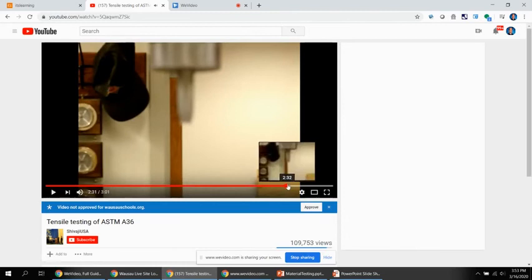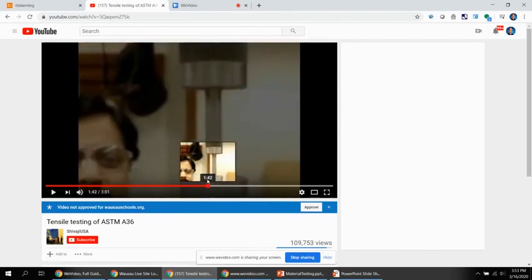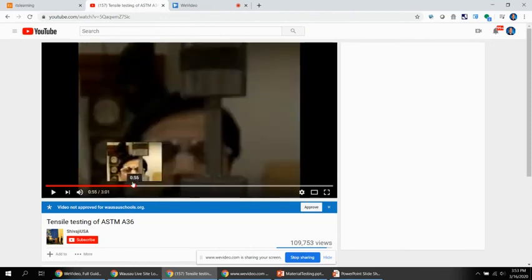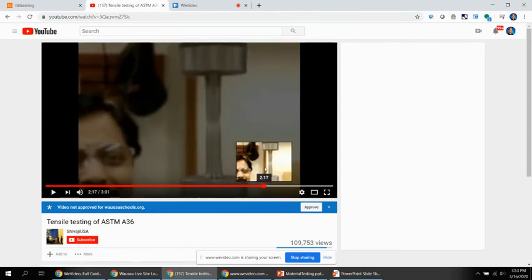I'm going to pause this for a second and back this up. You're going to see how much that does, in fact, deflect. This is our original length, and as we stretch out, you can see that this test sample really has stretched quite a bit. This point right here is the point at which failure has occurred.